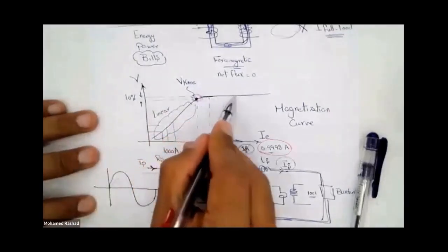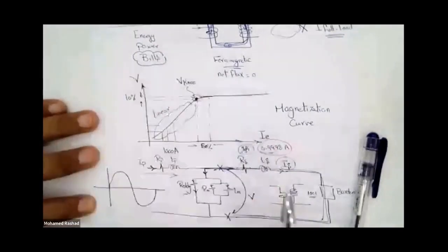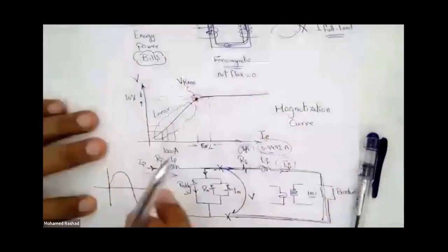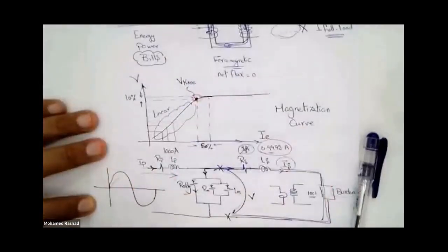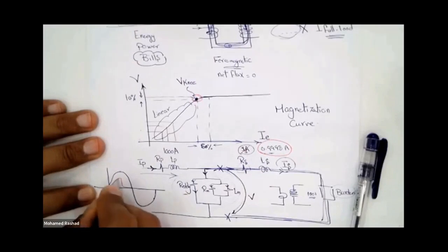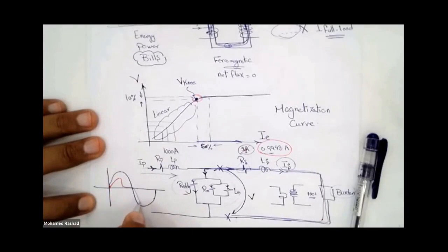As soon as it reaches this stage, all these dipoles have been arranged. You no longer have dipoles to arrange, so you don't have dΦ/dt. No flux is transferred from the primary to the secondary, so the current increases like this, then decreases back to zero, and then in the secondary it increases again like this, then decreases back to zero. So this shape means that distortion has occurred.